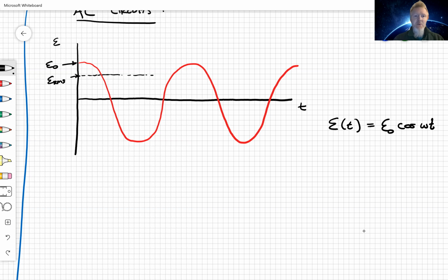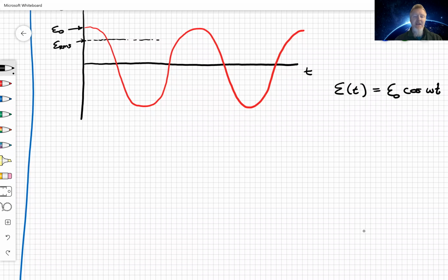What's nice is we like to represent this in what's called a phasor diagram. I think, and so do lots of other people, that phasors are great because they prevent you from having to do all this crazy trigonometric identity adding. What if I wanted to add a cosine to another cosine with a different frequency? Or add a sine to a cosine? You'd have to look up all these blasted trig identities for the adding formulas. But if you use phasors, it's just like adding vectors, and it makes the whole process much easier, at least in my opinion.